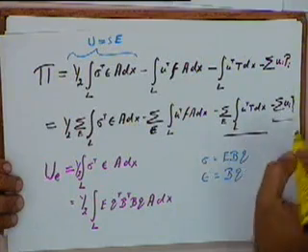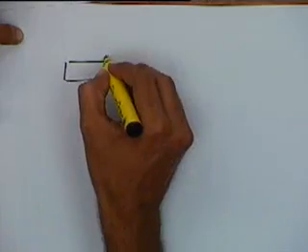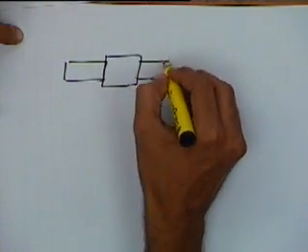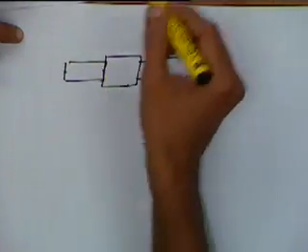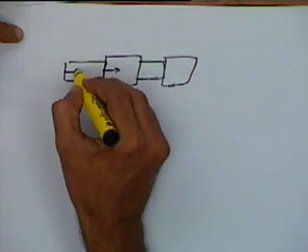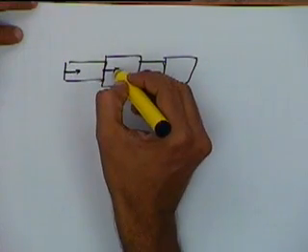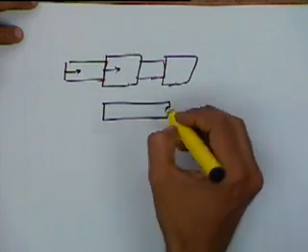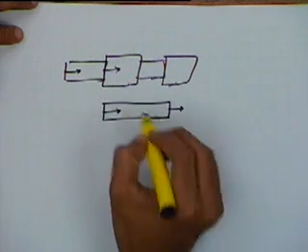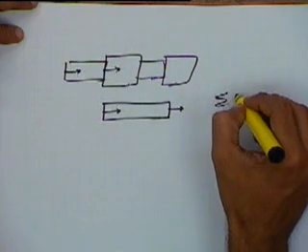that is this term, sigma ui pi. In this, if we have a set of elements and so on, we can assume that all our point forces will be acting on some of the nodes. Okay, so the point force is acting only on the nodes. So if we have some element, then we can have some force acting here and we can have some force acting over here. Okay, so the contribution of the last term, sigma ui pi,